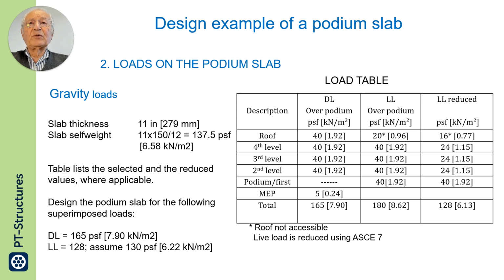Now we move forward with the gravity design first. I have the dimensions given in the previous slide. Here I have the load. The load is summarized on the table on the right. The dead load is based on the slab thickness. In addition, there will be a partition load.